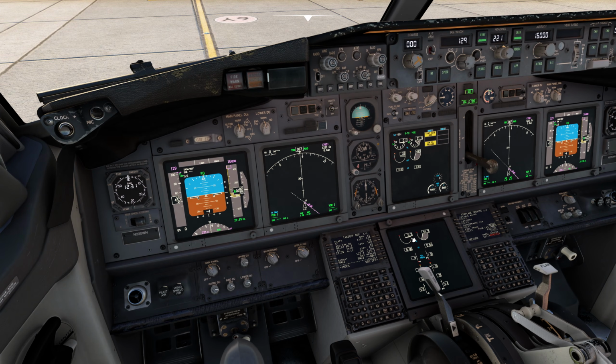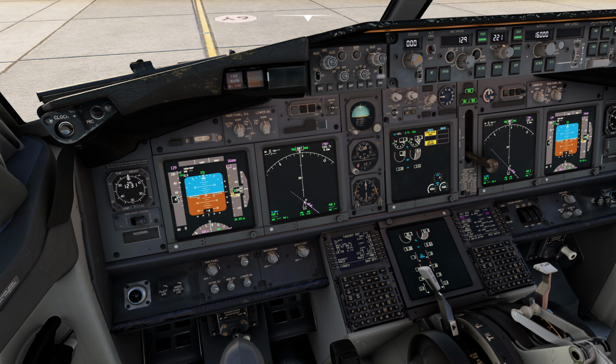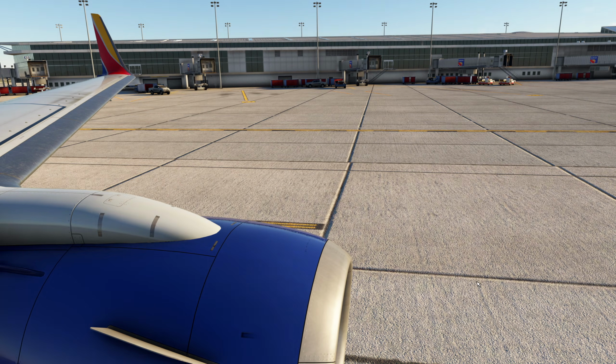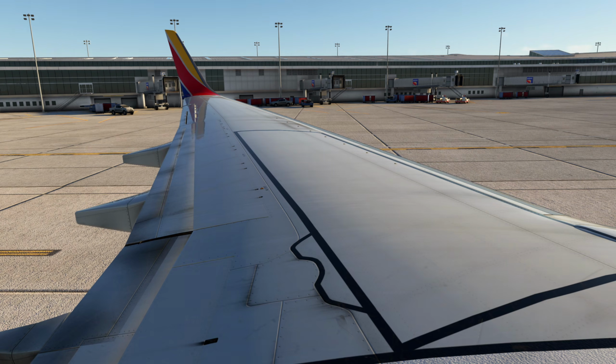Looking for N1 to rise between 20 and 25%. Unlocking gear. There's 20%, and introduce the fuel. Tow truck disconnected. Bypass pin removed. Left is clear. Right is clear.